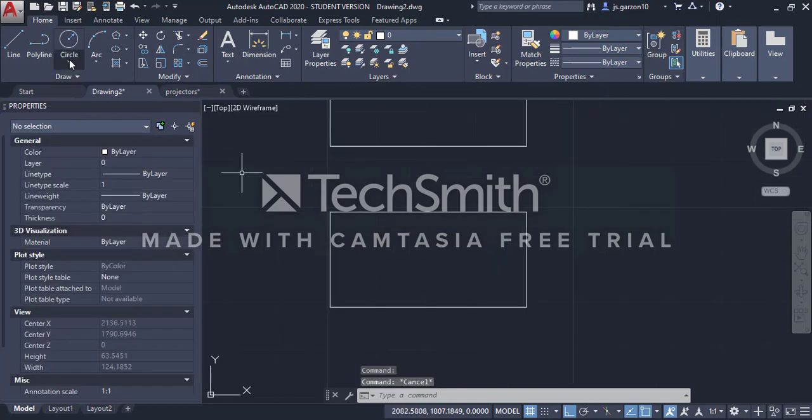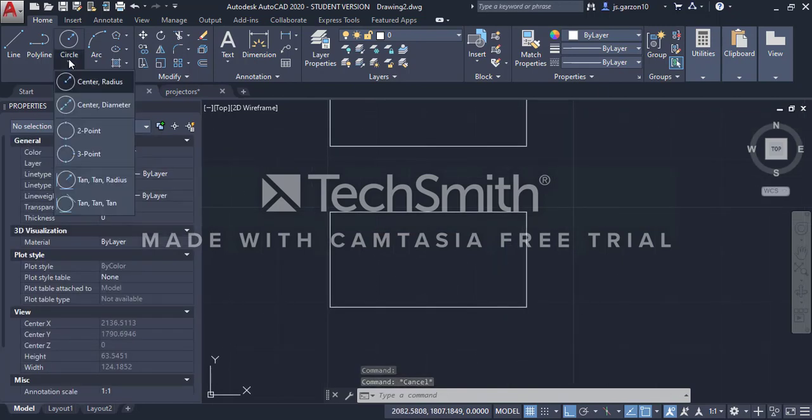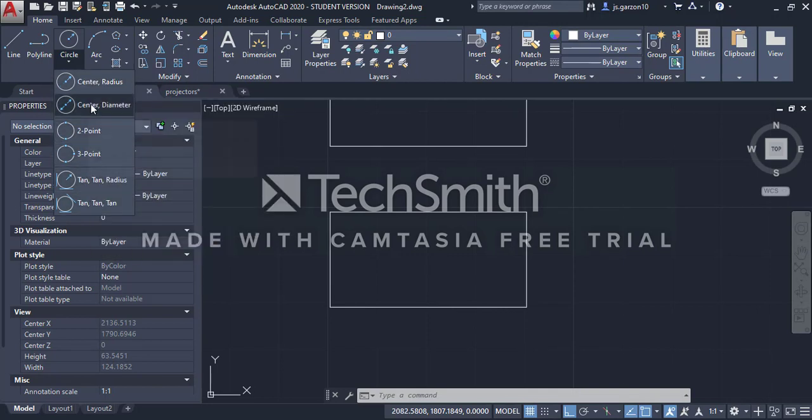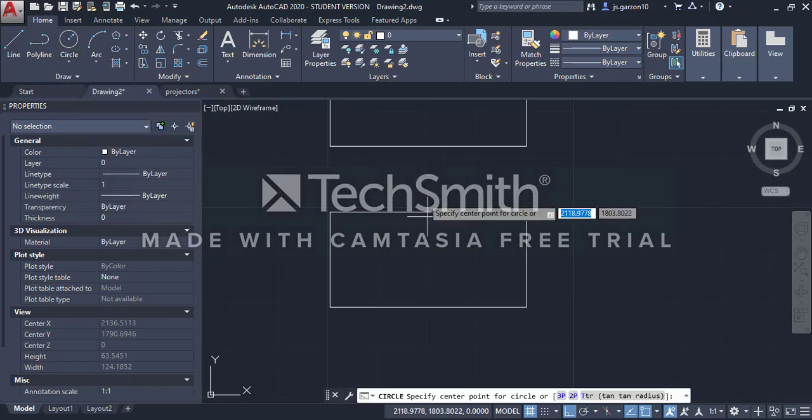If you want to draw a circle, you have different options. The difference between all of these options are the inputs. You can input the center, the radius, center diameter, 2 points, 3 points, and tangents. So here we are going to specify the center and the radius. As you can see at the bottom, it will ask you for instructions. First, specify the center of the circle.